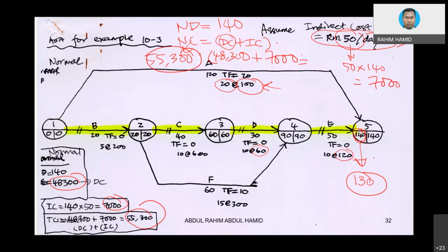First step, we look at the critical path, and only those activities on the critical path will have a direct influence on the overall project duration. The others we don't need to consider. There is one more consideration, the lowest cost slope, but here the lowest cost slope within the critical path should also be okay. But then the issue is, which activity?